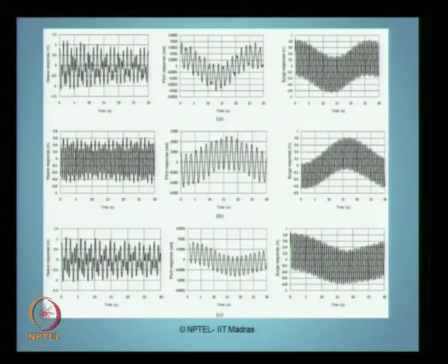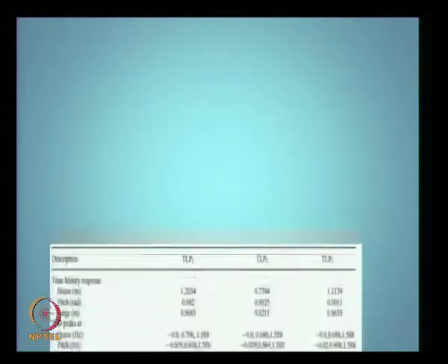And these are my results. The left hand side curves show heave response in meters, this is pitch response in radians, and this is surge response in meters. You will see in most of these cases the heave response is more varying, whereas here there can be a specific order. Heave response is getting more exercised in this specific example because of 0.46 radians per second, 0.46 hertz, which is matching with the frequency of heave.